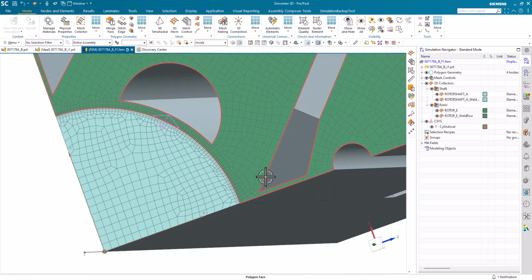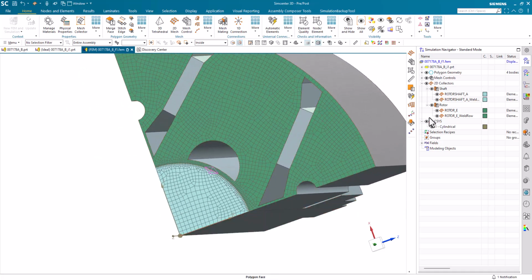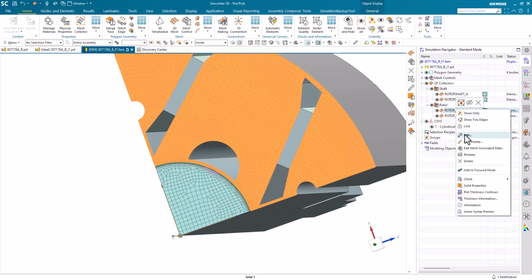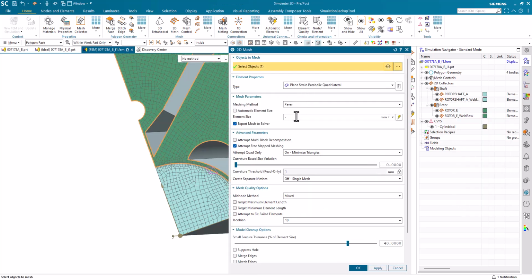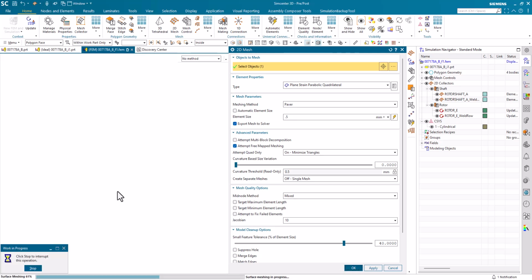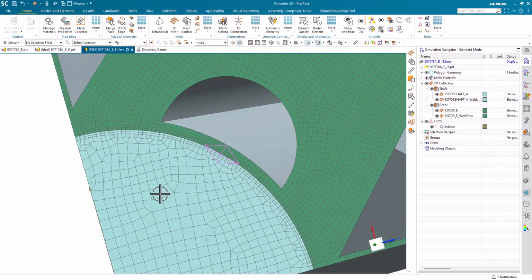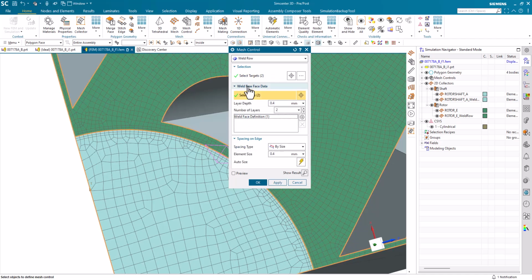Then I've got that mesh as well. So maybe I should have edited that element size from 1 to 0.5 just to get a little bit more detailed capturing of the geometry. Also, if I look in this region, I can pave this edge here. So I'll edit this and pick that definition, and then for its edge, I'll add that edge in there as well.